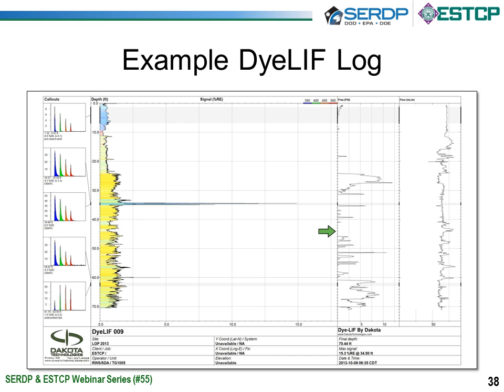One thing I'll mention here too is that since we're injecting an emulsion and a fluid, we can monitor the injection rate and the back pressure. So the injection rate divided by the back pressure is proportional to the hydraulic conductivity. And so that's another very useful parameter that is now routinely measured with this tooling, this index of hydraulic conductivity that you get by just measuring the injection rate and the back pressure.